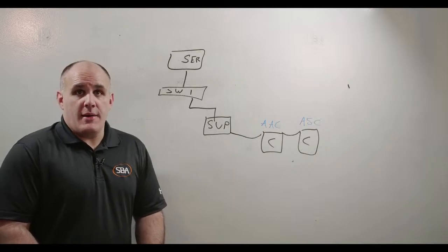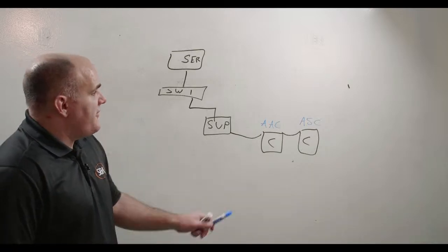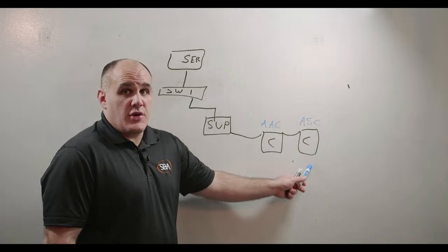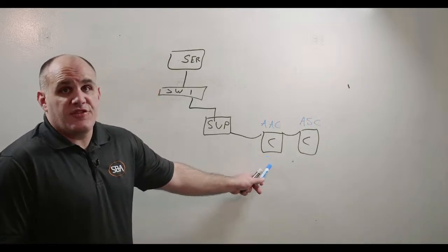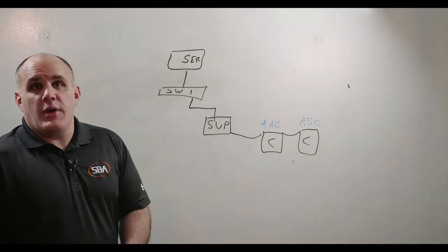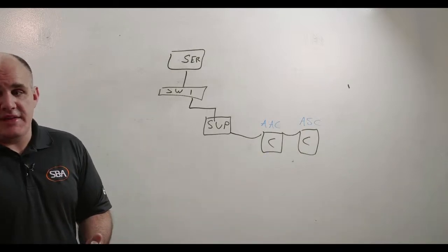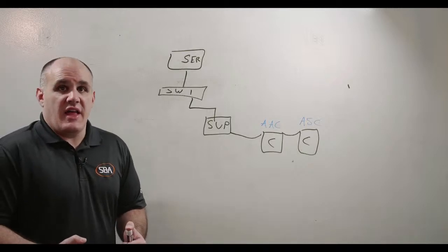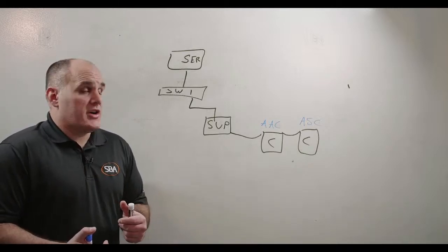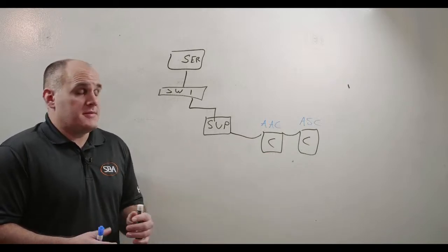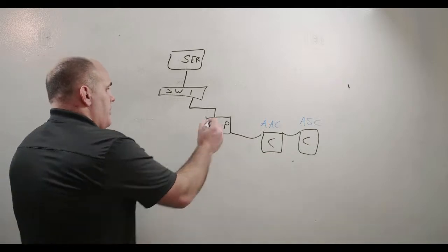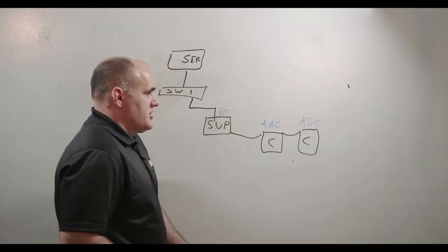Supervisory devices' capabilities have expanded way beyond that, in that now they allow visualization of data, trending, data analysis, and some global level programming. Whereas oftentimes in ASCs you'll do configuration, although some of them are free programmable, AACs are almost always free programmable, but they also have some building controller capabilities. Now we'll talk a little bit later in this live stream about a three-tier architecture that uses AACs in lieu of BCs. So a BC, a building controller, is going to be your supervisory device.